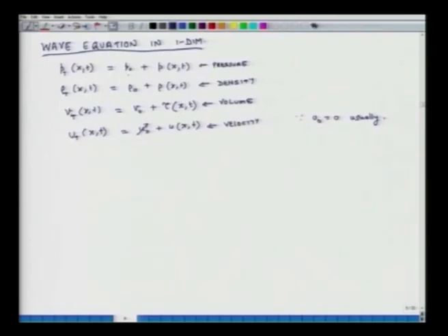Also, it is important to provide some values at this point of time. So, my P naught equals approximately 10 to the power of 5 newtons per square meter. My rho naught, which is the density of air at MSL, is 1.18 kgs per cubic meter, and the initial volume could be variable, because I can consider as much volume as I want.